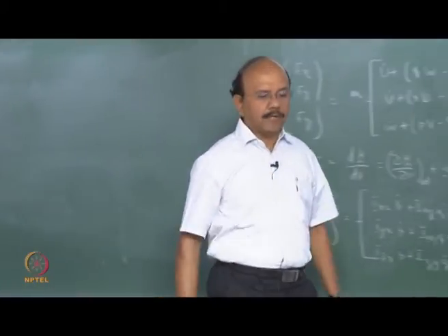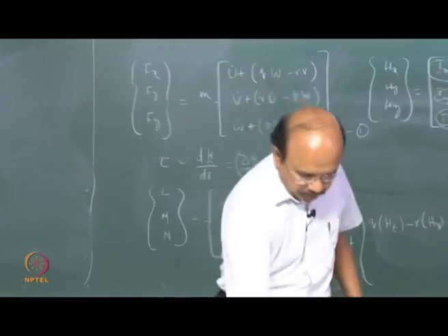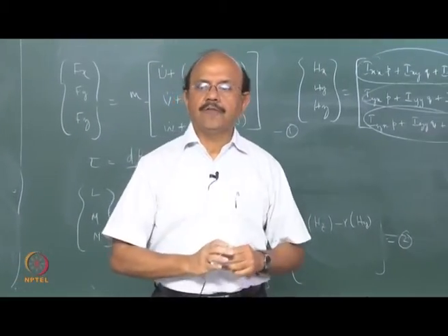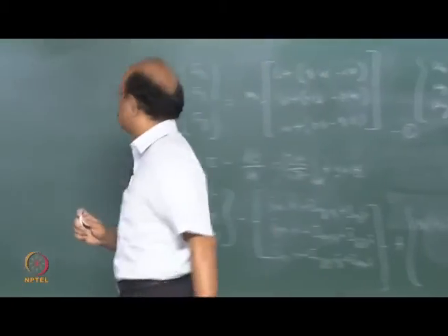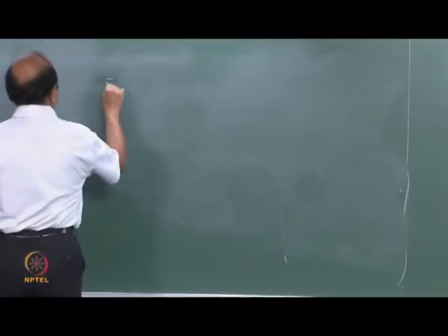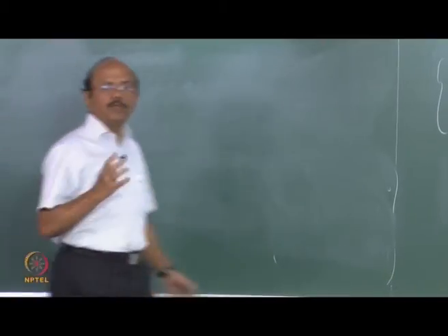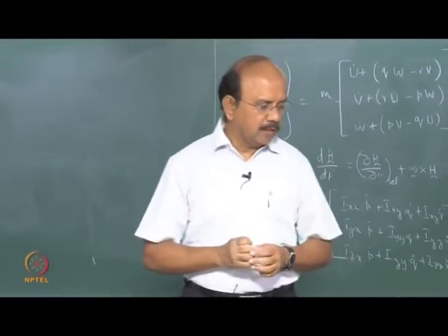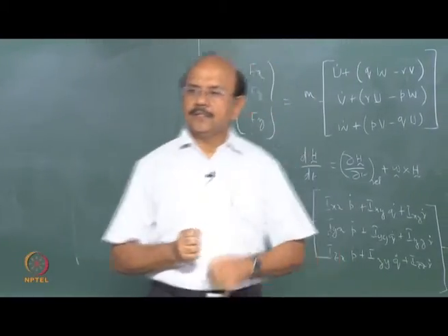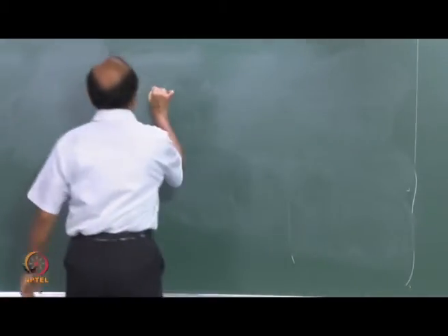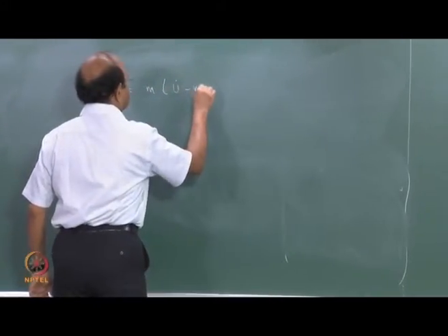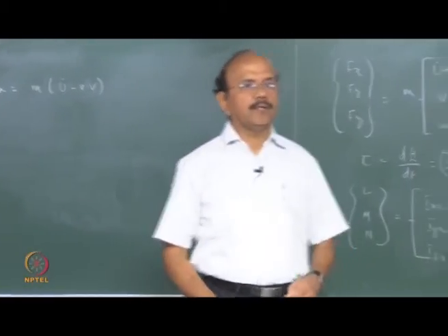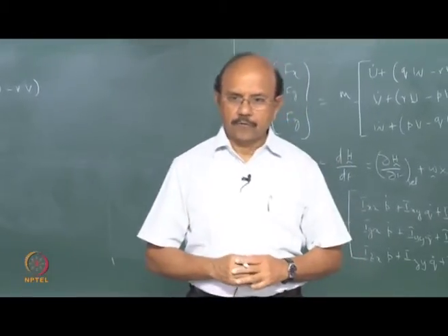So let's see. Write down what is the expression which I can use. Fx and Fy. Fx, that is the longitudinal force in the longitudinal direction, which we had already seen. But with respect to the body-centered coordinate, it is m into (u dot minus rv). So that's the body-centered coordinate expression for longitudinal forces.